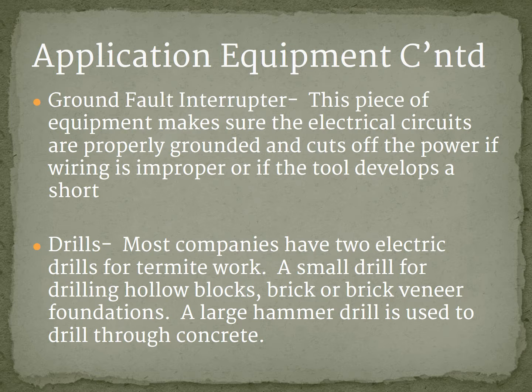Another tool, obviously, that you're going to have to do termite work is going to be an electric drill. And the type of drill you're going to need is obviously going to be a brick or a concrete or masonry drill to be able to drill into brick veneer, block, and things like that. A lot of people will call it a hammer drill as well, but you got to have the right drill and the right bits to be able to do the job.